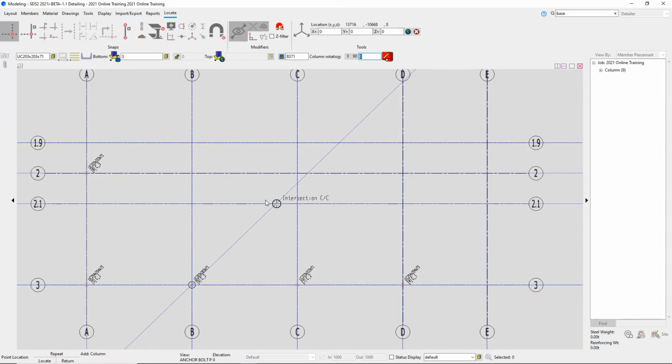And then we can come locate those two columns at B2 and C2. So I'll just left click at B2 and I will repeat that command at C2. So I will middle click at C2 here.